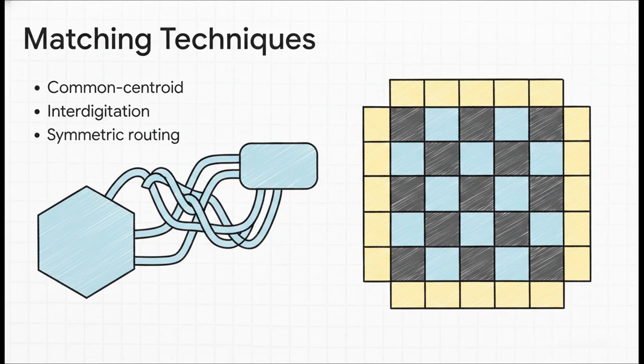We also surround them with dummy devices. These are sacrificial transistors slapped on the edges that literally never turn on. We add them just so our active inner devices see the exact identical optical and physical surroundings during the manufacturing lithography process. And of course, you meticulously ensure symmetric routing and equal path lengths, basically guaranteeing that the parasitic environment is perfectly cloned across those matched paths.